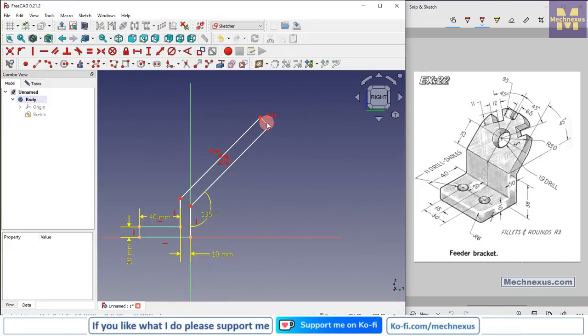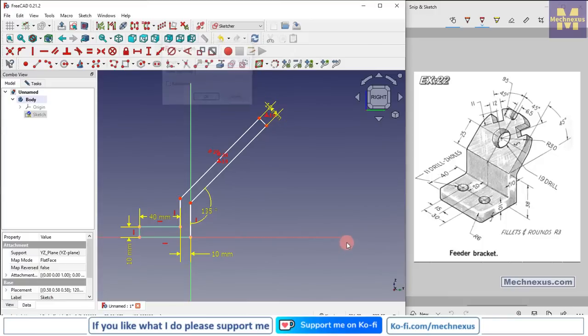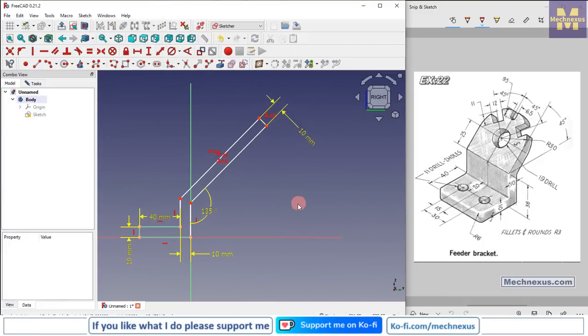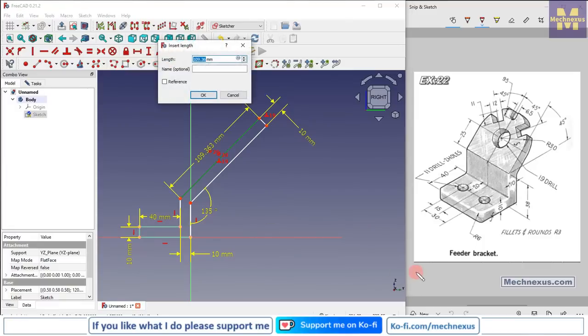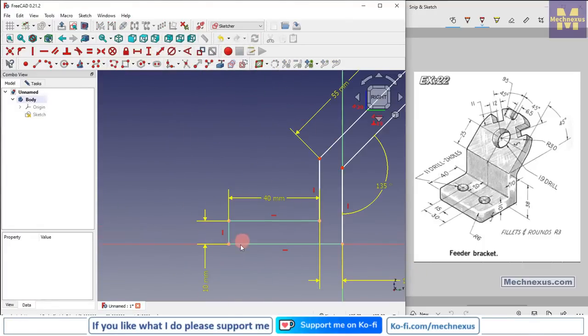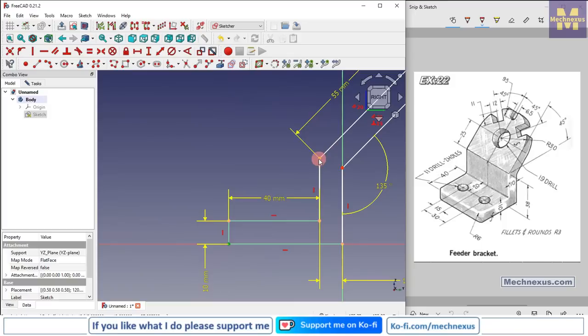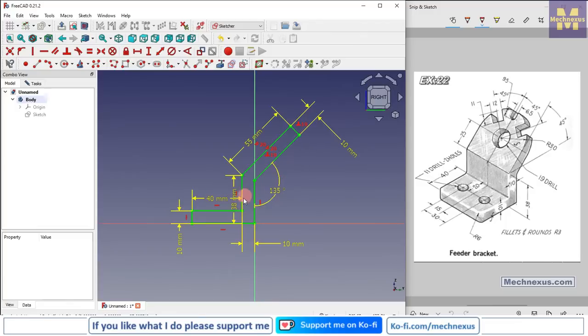Now select this line and add a dimension of 10 mm, and select this and add a dimension of 55, and from this point to this point is of 38. So our profile is fully constrained.